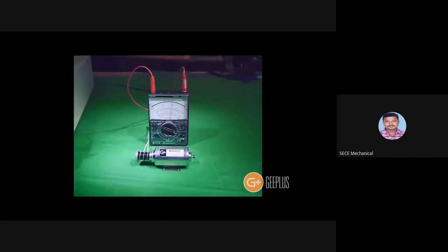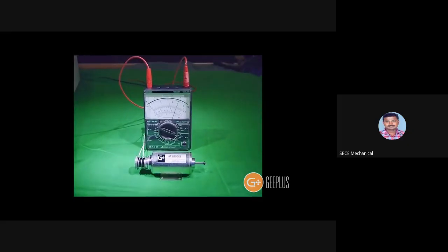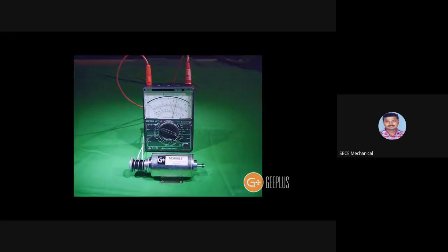Because this solenoid has been loaded with a spring that has a rising rate force characteristic, as the current increases, the force developed by the solenoid increases, allowing the solenoid to move proportionally to the current being applied. Because it's moving at a controlled speed, the noise at the end of the displacement is barely perceptible, as you can see on the sound meter here. While there is a steady background noise, any noise from the solenoid itself is insignificant.